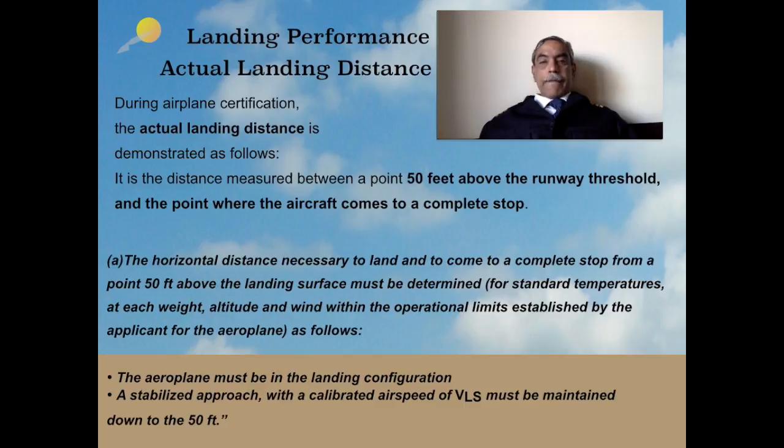He would be demonstrating, and it is defined as the horizontal distance necessary to land and come to a complete stop from a point 50 feet above the landing surface, and must be determined for different conditions, and the graph must be drawn or the tables must be given and published in the flight manual and supplied to the operators, and the pilot will be frequently referring to them for his day-to-day operations.